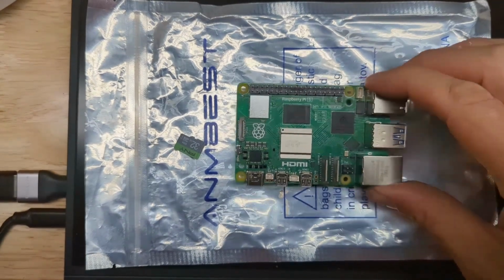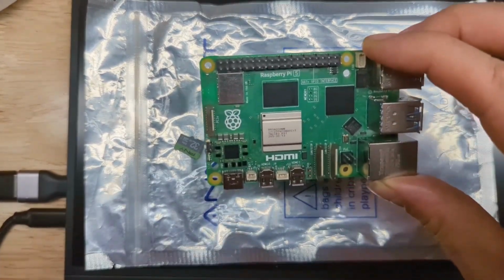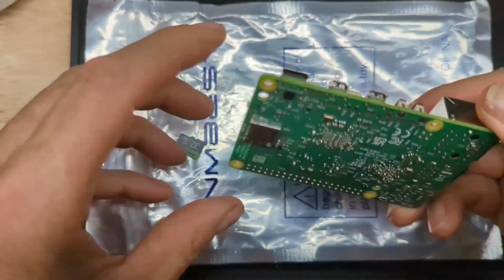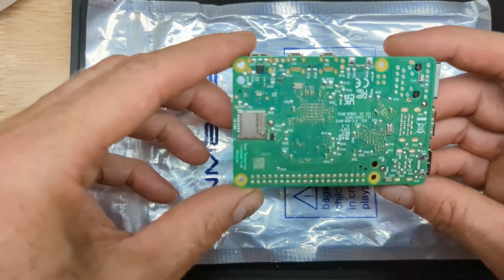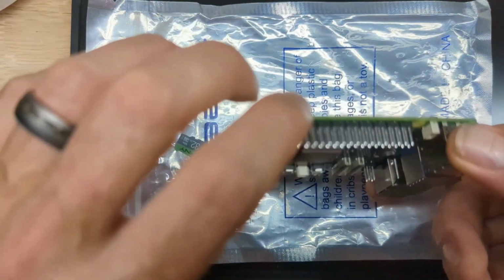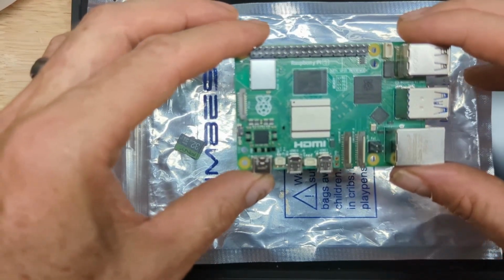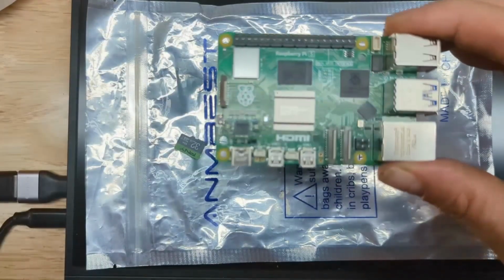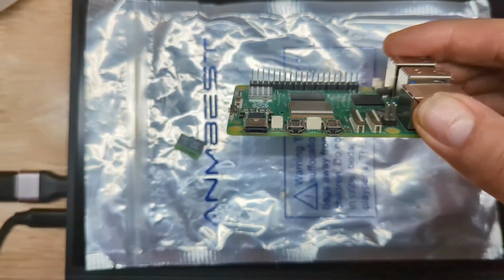Okay, we're ready to take a look at our Raspberry Pi 5 board. Now, if you've never seen or worked with any of the Pi computers, you'll notice the first thing is they're very small. Small but capable. One thing you definitely want to make sure is that you hold it by the edges. You do not want to grab it on the face or the back, because you have a printed circuit board on the back and you don't want to short it out. So definitely, while you're holding it, make sure that you're gripping it by the corners. You do not want static discharge to ruin your device.